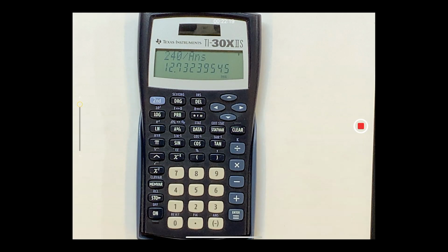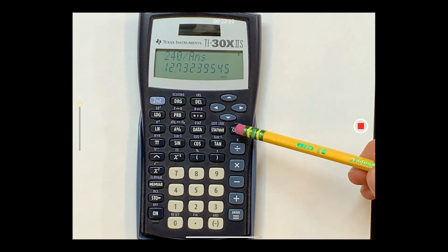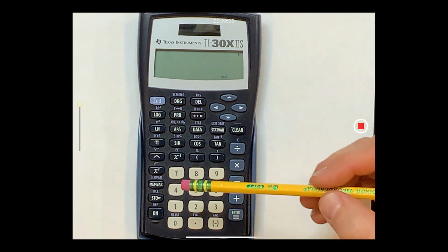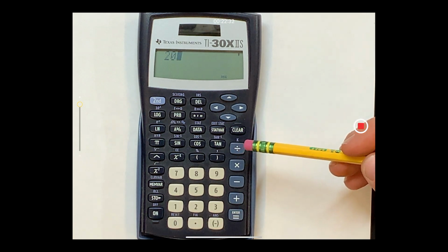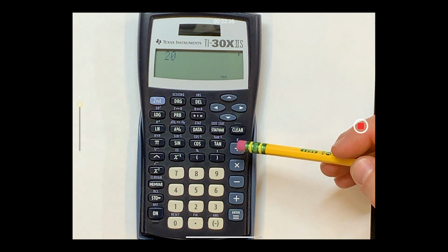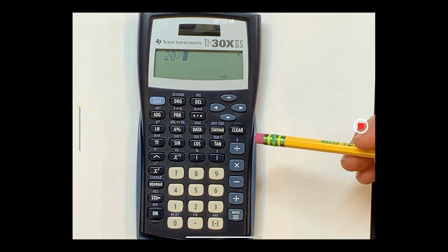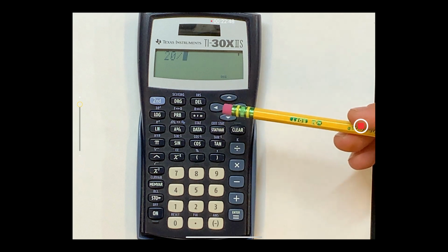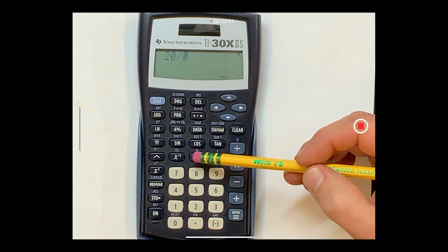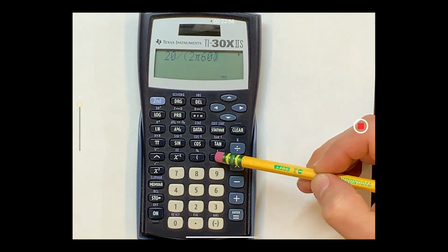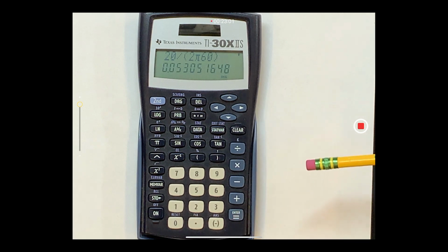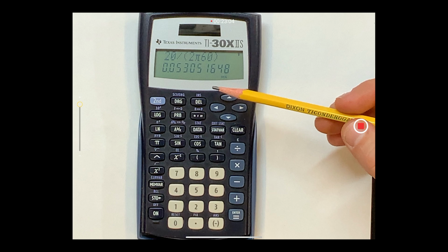So quickly back over to the calculator. Now that we're on a different problem, let's make sure we clear out what we had on the calculator and simply take the 20 ohms of inductive reactance and then divide it by 2 pi 60. Now be careful of order of operations with this problem, because if I just go ahead and enter 2 pi 60, it's going to divide 20 by 2 before it multiplies pi and 60. So we want to make sure we use some parentheses on the bottom. 2 pi 60, close the parentheses, and it shows us that we have 0.053.